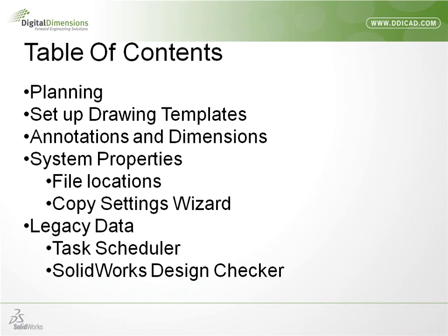I'll walk you through setting up the drawing templates. I'll show you how to link parametric annotations to file properties or dimensions. I'll take you through adding dimensions using the inserted model items, using the smart dimensions, or pulling in your DimExpert dimensions. And then we'll talk about the system properties.